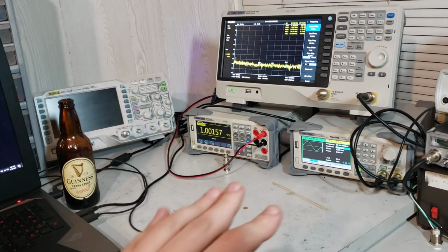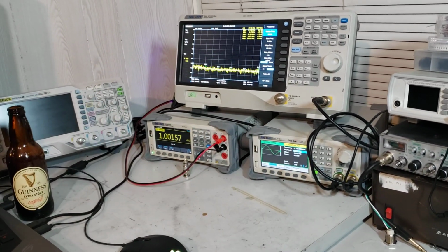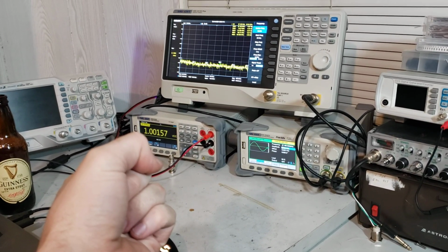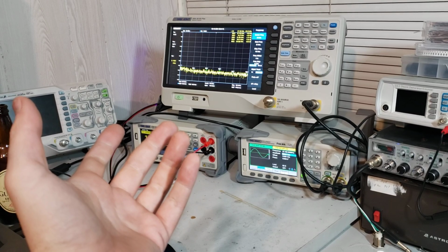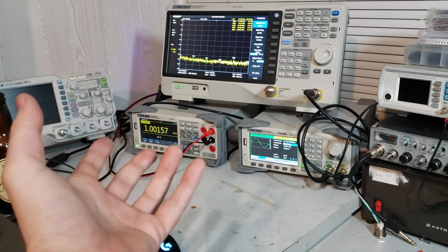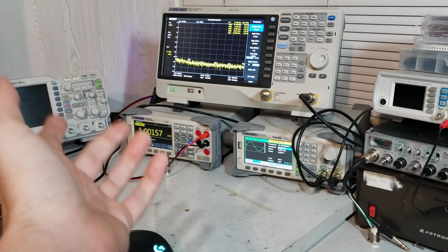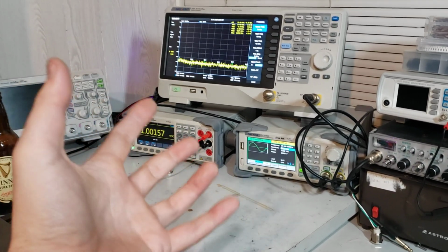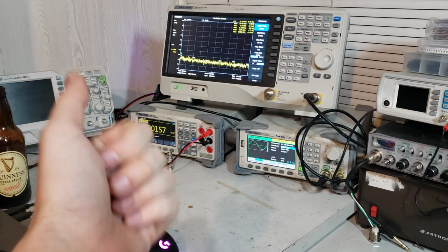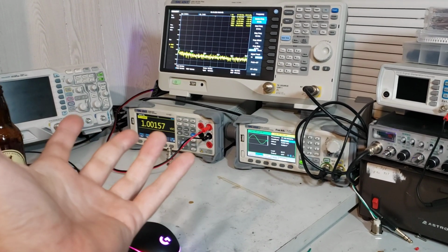So, the gist of this video is automating your test bench and automating measurements on whatever you want to measure. The reason that I'm doing this is because I want to characterize my projects. So if I build an amplifier, I want to characterize that amplifier and have a record of how that amplifier performed, what parts were on it, how it was assembled, intermodulation, distortion, overall linearity, gain, harmonic output, all that good stuff. I want to have a detailed record of that, and I want to automate that process, because getting those measurements manually can be very, very tedious, especially if you're measuring across different power levels and with different voltages going into the device and all that kind of stuff.